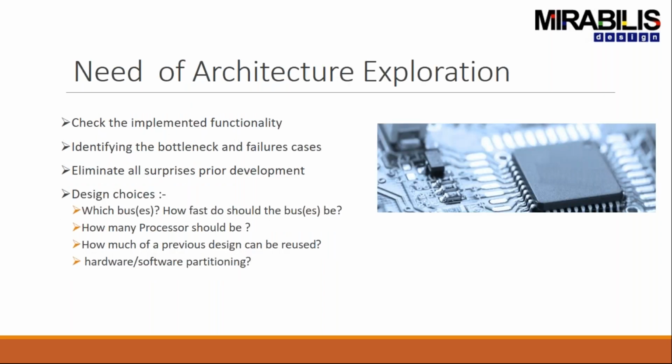Moving on, the first question that arises: what is the need for architecture exploration? The main motive of this webinar is to understand the need for it. Let's take an example. Let's say you have a block diagram design and you have to proceed to the next stage. Normally, verification of the design is done at RTL level. If we find any fault in the design at that point, then we have to come back and recalibrate the design, which is going to take a lot of time. In the end, a lot of resources and time are wasted going back and forth. All these scenarios can be avoided if system level verification of the design is done prior to development.